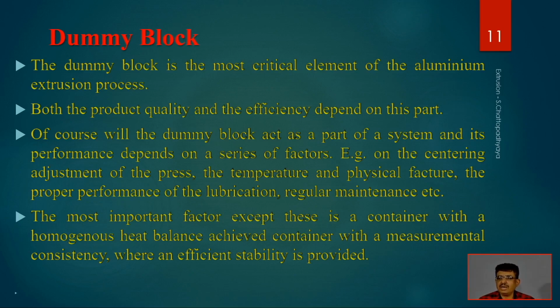So the dummy block takes care of all those things, and if it is a detachable one, modular maintenance can be carried out with some extra dummy blocks. While the extrusion process is going on, the other dummy block is getting cleaned, and whenever it is ready, within very little time we can change it. So this also gives some online setup time, which is very good for just-in-time practices like SMED, single minute exchange of die. The die changing times, repair and even necessary idle times can be reduced to a great extent with this modular design of the dummy block attached to the plunger.